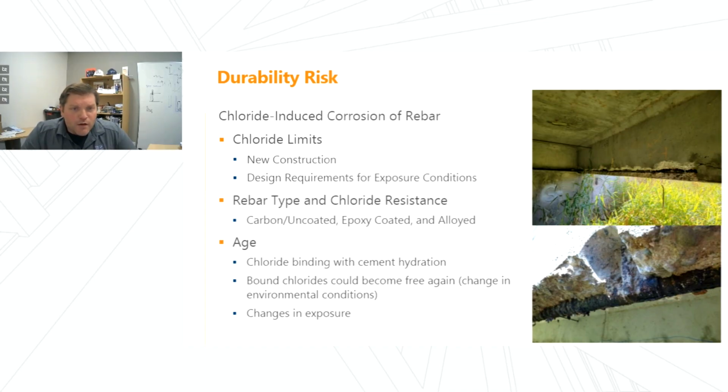We can also design our concrete appropriately, adjusting cover requirements or lowering our water-cement ratio to provide more durable concrete itself. We can also use different types of steel, whether that's epoxy-coated steel or alloyed steel, which will have a higher chloride resistance than conventional uncoated rebar.